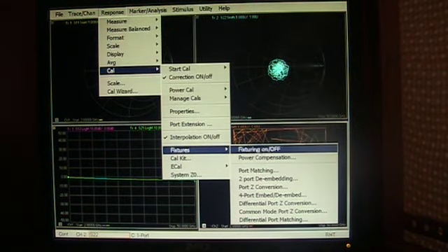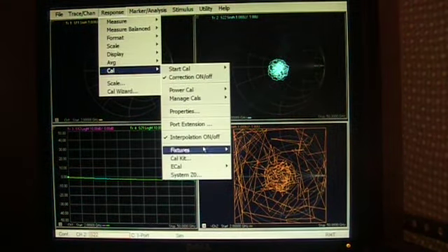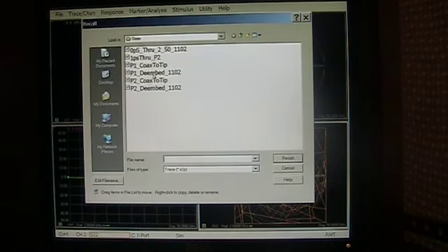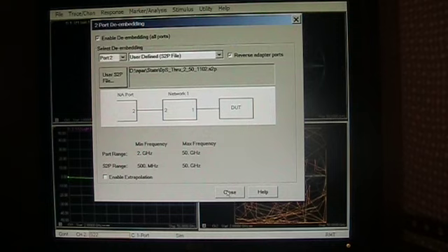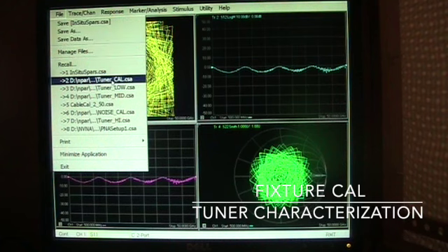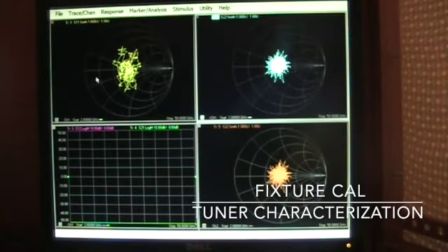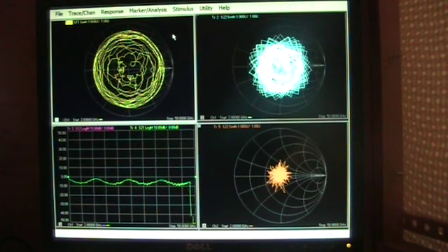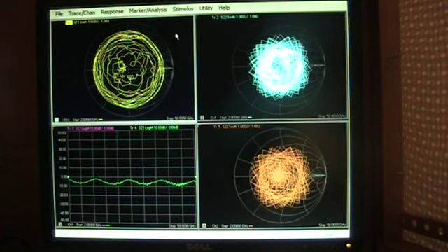So we'll say fixturing on, response cal fixtures 2-port de-embedding, enable port 2, user defined, reverse adapter ports, 0 picosecond through. Okay, we're going to go ahead and do a tuner calibration here. We're going to load the tuner cal state file, and we've set up all of the de-embedding from the previous step. So now it's a matter of just starting up the state file. First step that the program will do is it will copy this state file up to 3 times.